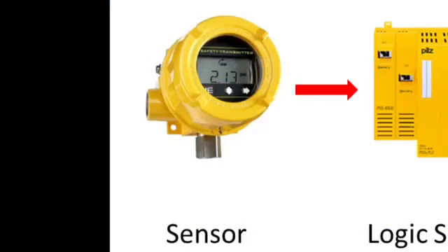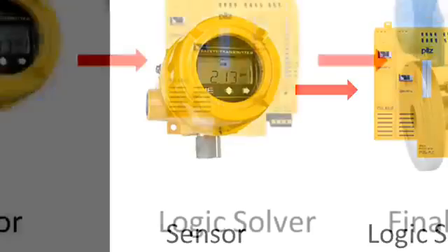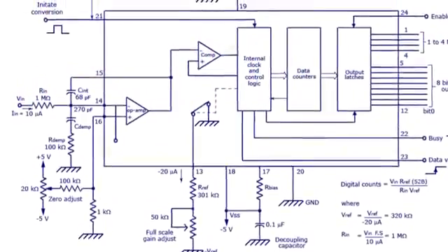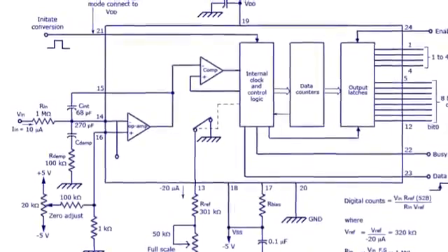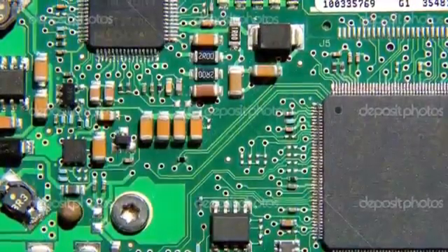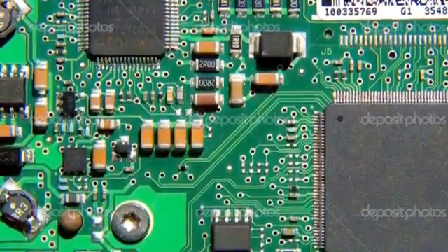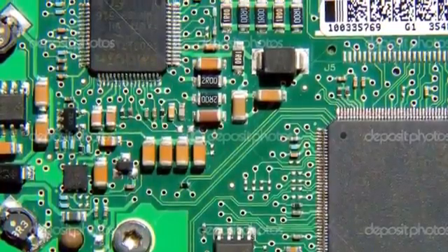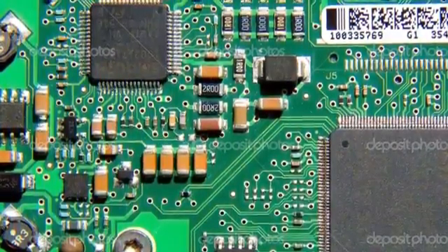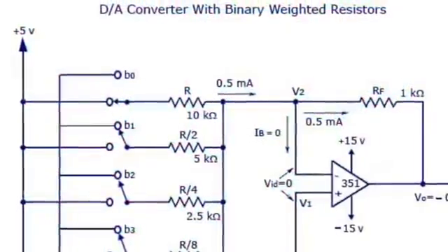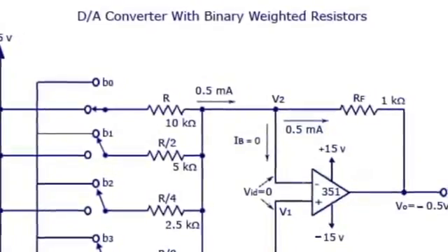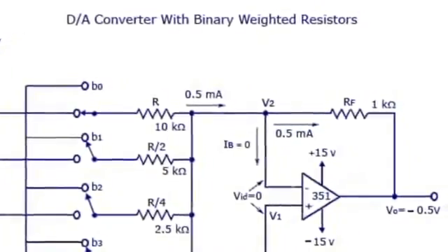For example, the sensor component must continuously monitor the process variable and provide this information to the safety PLC via a hard-wired connection. What actually occurs, however, is the analog signal from the sensor transducer is converted to the digital domain for processing. Digital signal processing occurs inside the transmitter's electronics to adjust the signal for ambient and process temperature conditions, sensor response errors, signal filtering, user settings, sensor calibration, and a process variable display, to provide just a few examples. The resulting conditioned and processed signal is converted back to the analog domain to retransmit the 4 to 20 milliamp signal over the hardwired connection to the safety PLC.